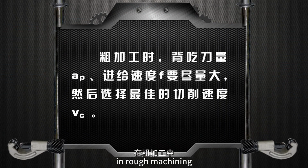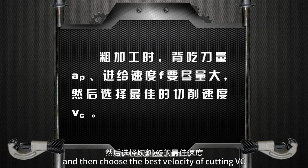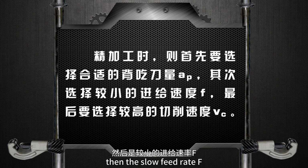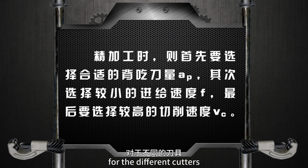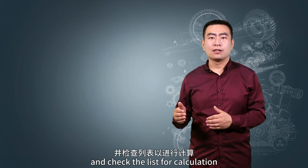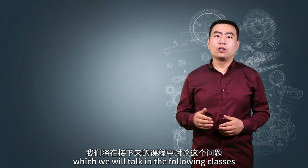In rough machining, the back cutting amount, AP, and feed speed, F, should be as large as possible, and then choose the best velocity of cutting, VC. In precision machining, we need to choose a proper back engagement, AP, at first, then the slow feed rate, F, and finally the high velocity of cutting, VC. For the different cutters and the cutting parameters of different workpieces, we need to decide through experience and check the list for calculation, which we will talk about in the following classes.